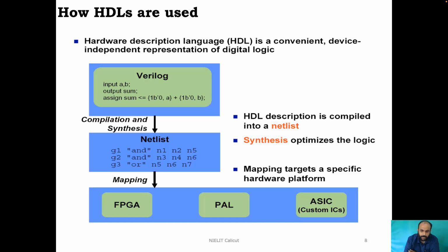There is a difference between RTL designing and behavioral designing. RTL designing here stands for register transfer level. By that, what is meant is writing a Verilog description of a hardware in such a way that it can be converted to a structural equivalent by the process called synthesis. So we write a Verilog description in the RTL way, or in the synthesizable way, and put it for synthesis. The synthesis tool reads and infers your Verilog code. It finds out what should be the equivalent hardware structure, or the gate level netlist, we call it.